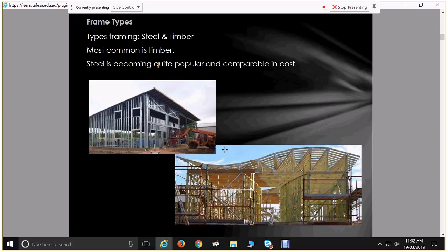But what you do see is other structural approaches, and we'll cover cross-laminated timber later on, but other uses of timber where we get plywood, cross-laminated timber, all these sorts of things that can actually just be made by robots in a factory. So we get CNC routers that are controlled by a computer program. You can say, we do the drawing, it's this thing, okay, robots and machine, build that for me, and then that all happens like that. There's certainly efficiencies that can happen in that regard. We'll get to all that later. When it's your simple, fairly cheap residential timber, largely happens on site unless it's your timber roof trusses.